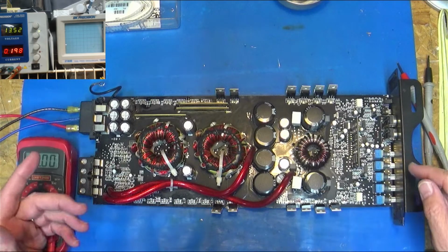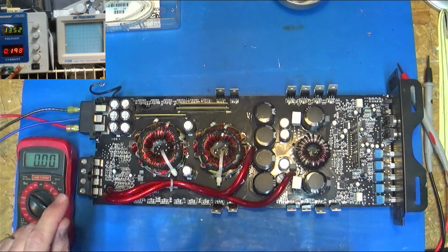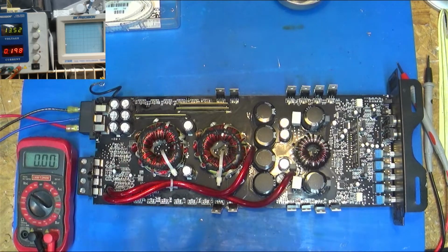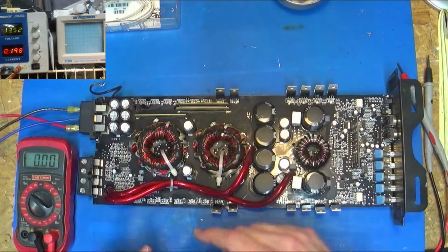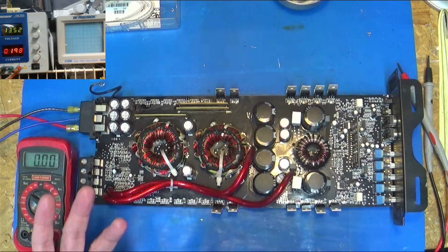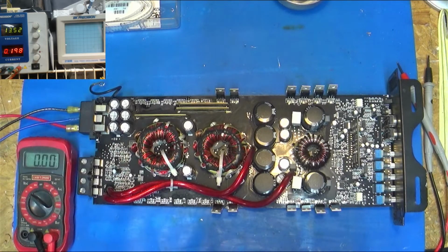So, follow up to the live stream, we were working on this Audiopipe 1500. We had determined that we weren't getting any pulses and we weren't getting a correct amount of power to the TL494 chip to produce those pulses. Now we've already removed all the FETs and all the pull down resistors and all the gate resistors. Everything had got fried. And I said, well, I'll have to draw out the remote turn on circuit. We were looking at it and it wasn't getting power to this chip.